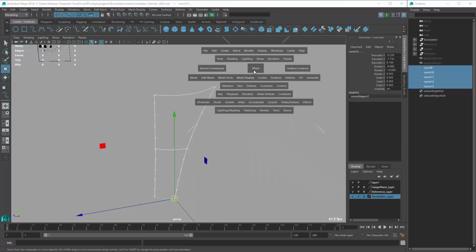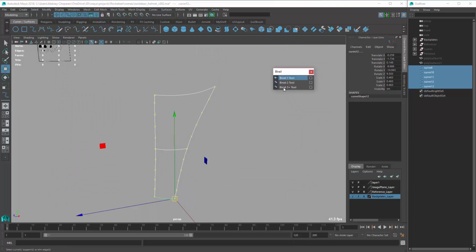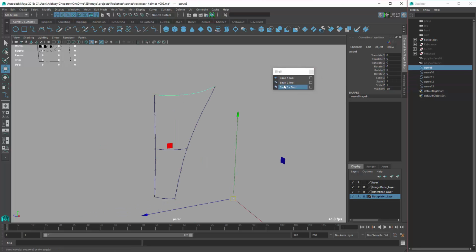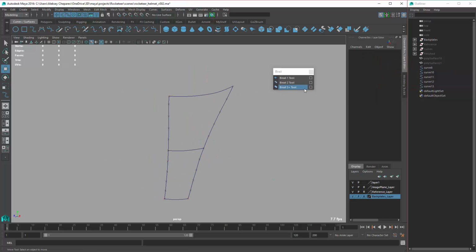It's actually pretty easy to do. Once you know how to use one NURBS tool, the rest work exactly the same. So we need to find surfaces and find the bi-rail, and there are 3 bi-rail tools. Bi-rail 1 means that only one profile is being used. Bi-rail 2 means 2 profiles, one at the beginning, one at the end. And bi-rail 3 plus means that you can use 1, 2 plus any number of middle profiles. And this is the tool we'll use.